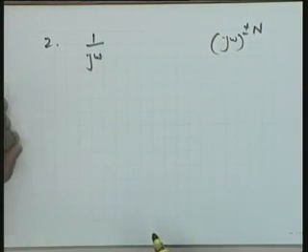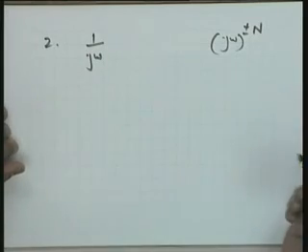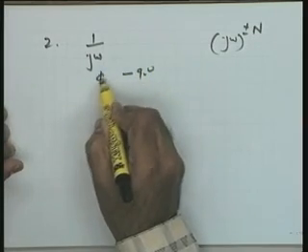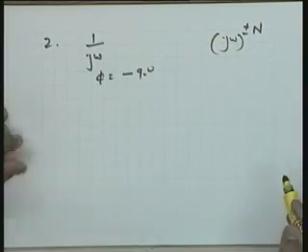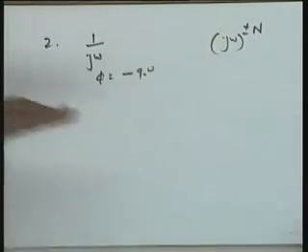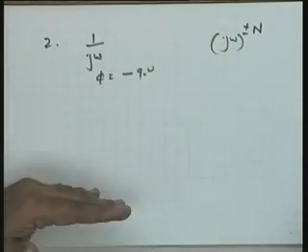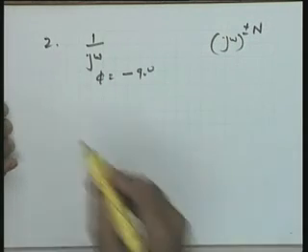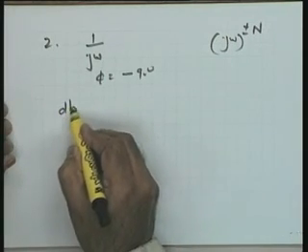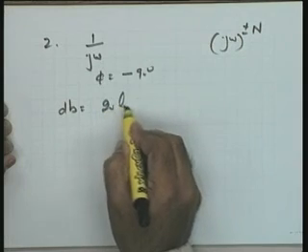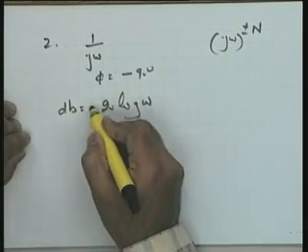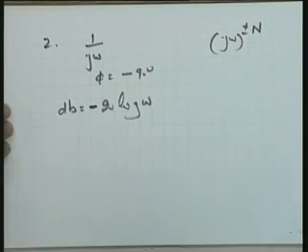So in this particular case, please find the phase angle picture is very clear. It is minus 90 degrees, phi equal to minus 90 degrees. So it is going to be a horizontal line for all frequencies in the phase plot. I need not plot it. Let me look at the magnitude, please. The magnitude is dB equal to 20 log of 1 over omega. Please see, dB is equal to minus 20 log omega.